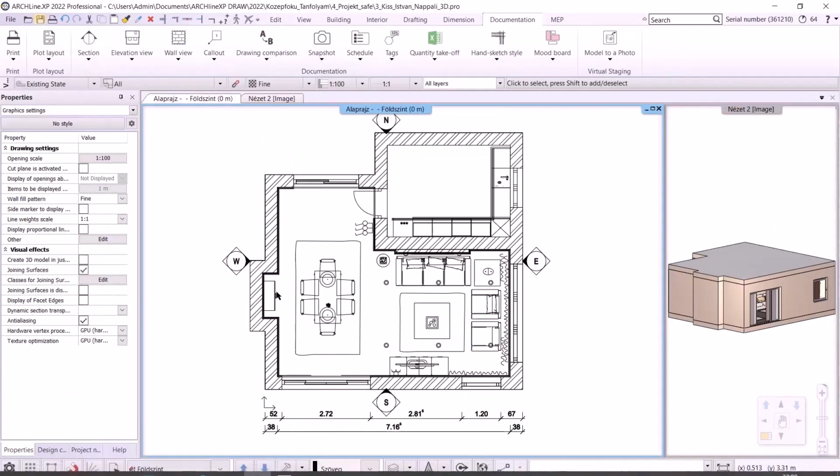The first thing is to check if there are 3D solids in the project. If there are, I need to delete them. The second is if there are objects in the project that are too big. When I download an object, the program warns me if the surface area exceeds 50,000. The third is whether there are objects with too much material. More than 50 materials are a lot. The fourth step is to delete unnecessary materials from the project.